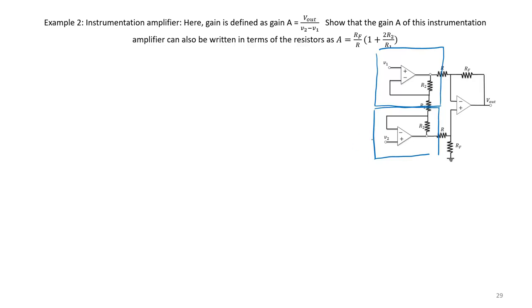So in this case, we know that our inputs are non-inverting amplifiers. And the output produced by those non-inverting amplifiers, these have some initial intermediate output voltages, and these will be sent in to a difference amplifier.